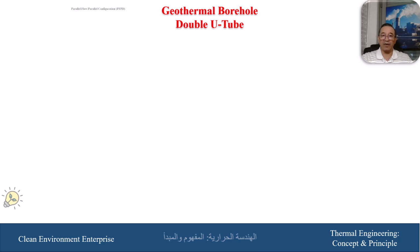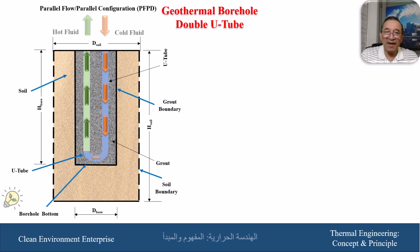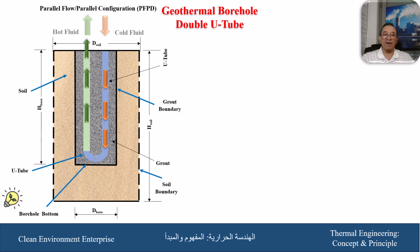The main structure of the double U-tube heat exchanger is composed of a borehole and double U-tubes installed inside this well, and they are surrounded by a grout material which should have good thermal conductivity to pass heat through this material between the fluid inside the tube and the surrounding grout and the soil material.